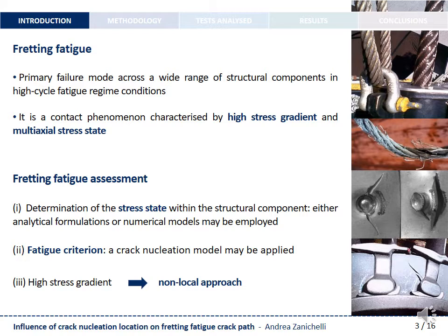Finally, due to the high stress gradient in the vicinity of the contact zone, it seems more appropriate to analyze suitable quantities summarizing the stress field related to a process zone instead of examining the fatigue load history related to a single point. Moreover, it is important that the fatigue assessment is performed in a point located at a certain distance from the contact surface. Therefore, a local approach should be employed in conjunction with the above fatigue criteria.